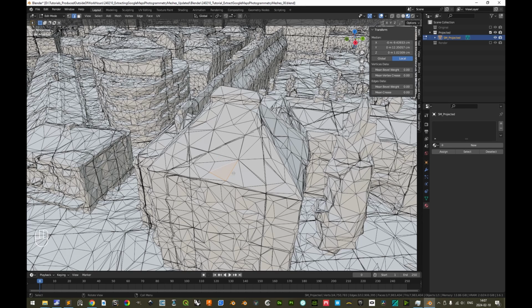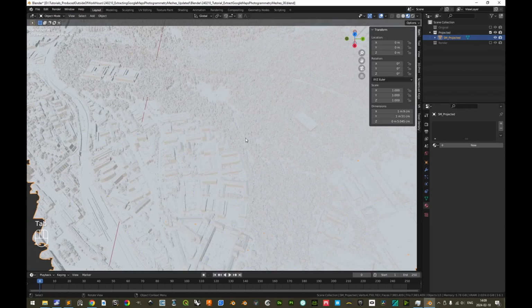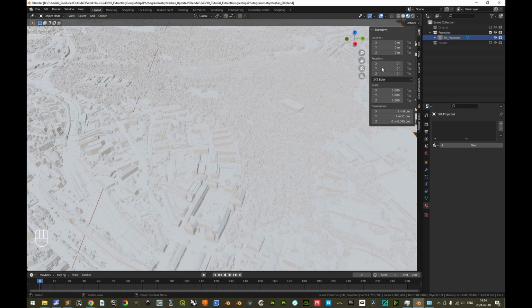Since we don't have this original triangle in the imported original mesh either, what will happen during the texture projection here will not be something magical, but we'll have to see the effect of that later. Press Tab to exit edit mode and re-enter object mode. Before we can project all of the textures of the originally imported mesh to the duplicate mesh, which should only have one singular material slot, we first need to properly unwrap this to-be-projected mesh.